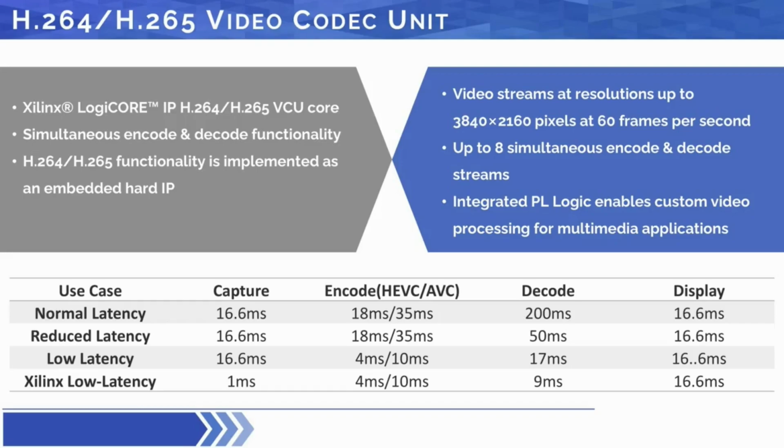The video codec accurately encodes and decodes the H.264 and H.265 standards with the transcode ability of the EV variant, helping in reduction of bandwidth with no loss in quality. And using only the hardened engines and peripherals of the EV devices, the integrated programmable logic is available for product differentiation, which can be made use of for the best optimal use of your video processing algorithms, your filter overlays, and custom interfaces.